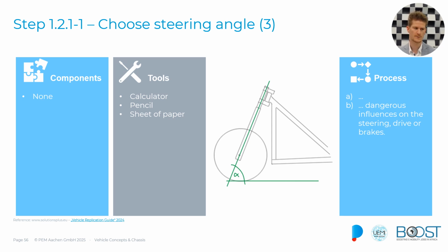It should always be borne in mind that if you have a lot of load on the front tire, steering becomes way harder. It will also suppress understeer, but you also increase the chance of tipping the vehicle over because it's just a three-wheeler. So make a wise choice of the steering angle at this point, depending on the road conditions you're driving in.